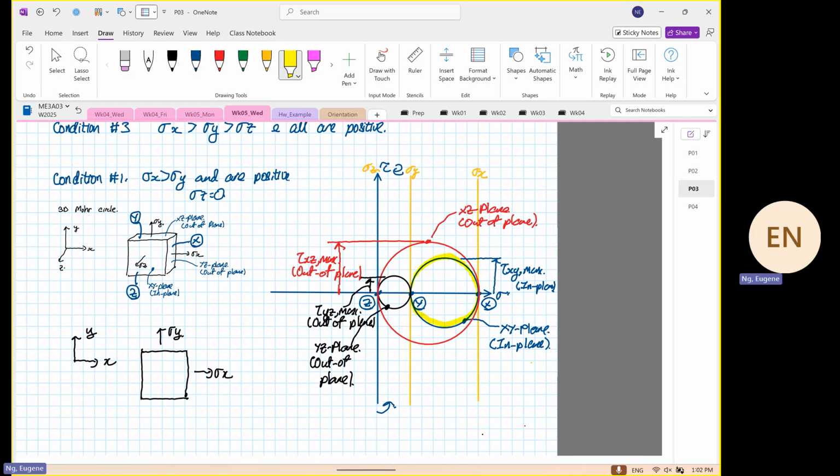Can you see shear XY max in plane? Is it the highest value? Stress Z is equal to what? 0. Then we sketch another circle. Once we do 3D Mohr circle, we realize that there is a bigger circle. Means, no doubt, stress Z is equal to 0, like what you see over there, it's going to generate a higher value. You can only get this with what?